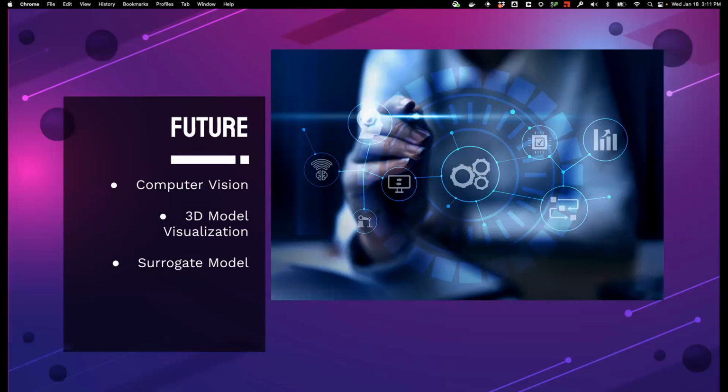I was even thinking if you could figure that out, maybe you could automate, and this wouldn't really be computer vision, the combining of rooms to simplify the model. If you had a bunch of offices along the south facade, you could just merge those into one big south office, and that would be sufficient from a thermodynamics point of view. Also, we wanted to include thermal model visualization in the Jupyter notebook so you could see the representation of what you were doing with the surrogate model, and then improve on the surrogate model itself.